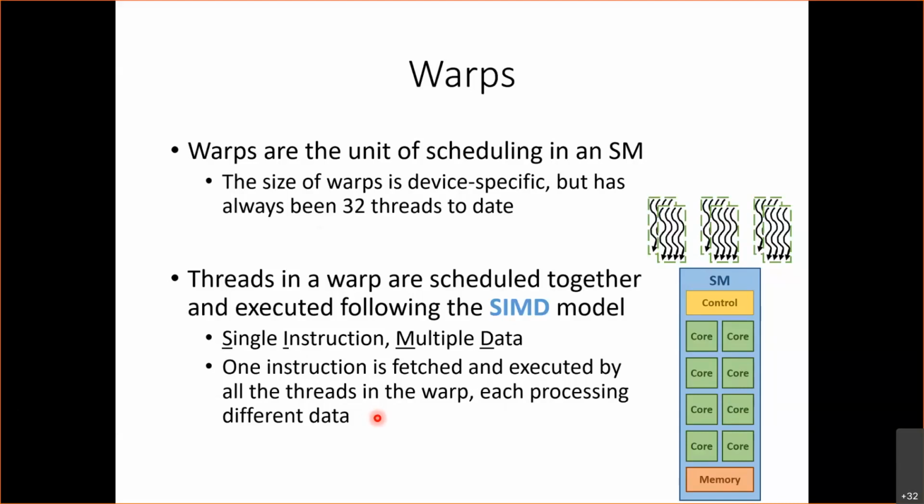Well, even if I was executing a different instruction for each thread, most likely they'll be going through the same code, so they will have a good amount of locality. But there's something more important than saving on the memory footprint of fetching the instruction. You save time and complexity of getting the data where it needs to go.